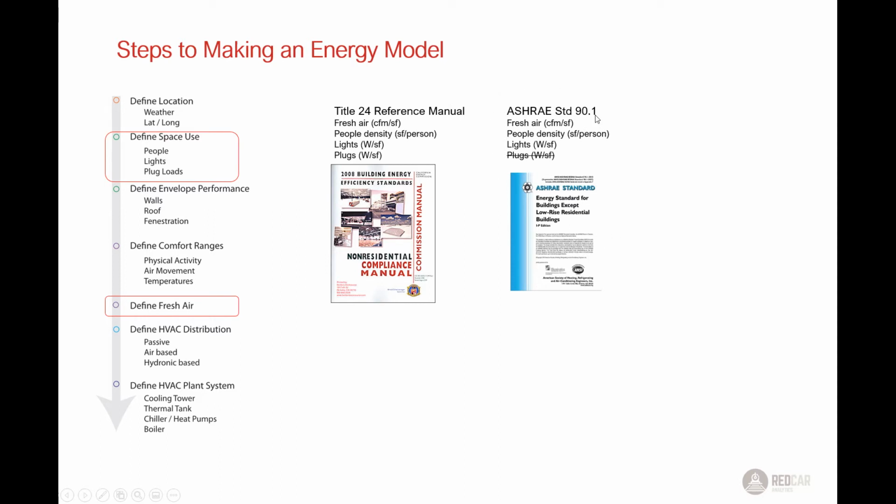Here, ASHRAE 90.1 is a standard created by ASHRAE that is used throughout the United States. Both of these give a starting list of common representative, they call them non-residential space types. So offices, conference rooms, corridors, and they give information about, well, how many people are usually in those spaces? What square feet per person would you expect? What's the lighting amount you would install? What power in watts per square feet of floor would that space have? And it includes everything from these density numbers to schedules that represent those spaces for usage.